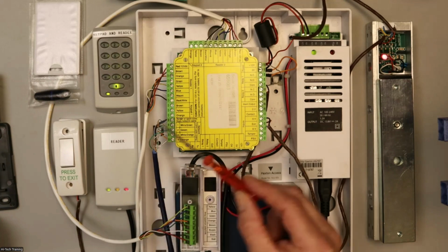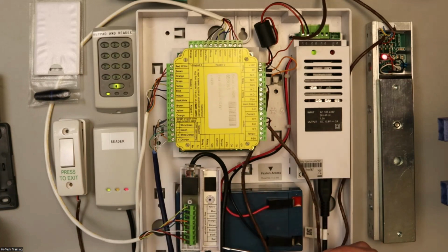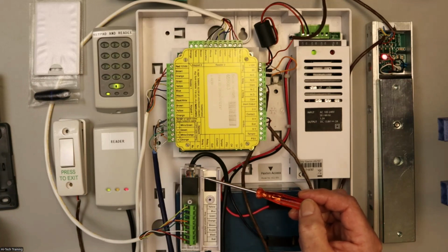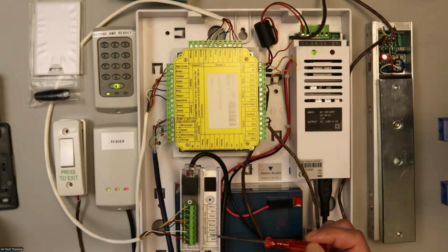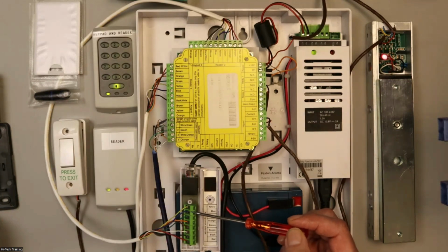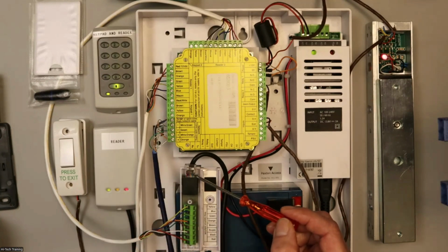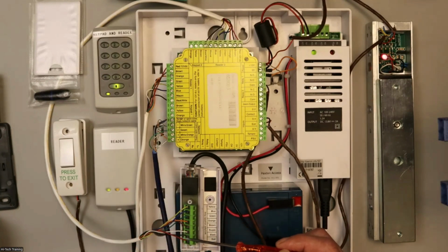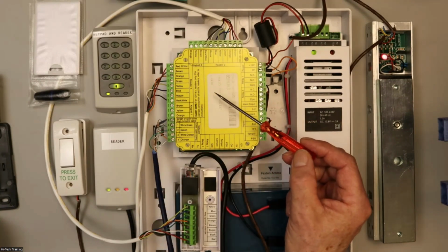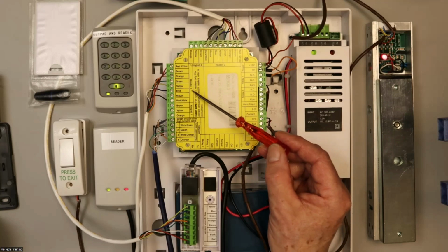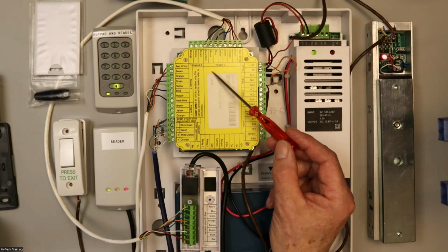The reader is connected on here via this little connector. First of all, we've got an RJ45 connector coming in here. Then you've got your colors: yellow, blue, green, orange, brown, purple, black, red, and so on. You put the colors from your cable here. So the reader gets plugged in here, and you connect to reader 2 or reader 1, whichever one you're going to use. Normally we use reader 1 for going into the premises and reader 2 for going out. You can change it, but that's usually the way it's done.